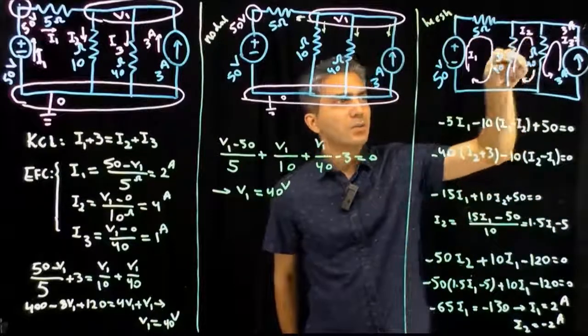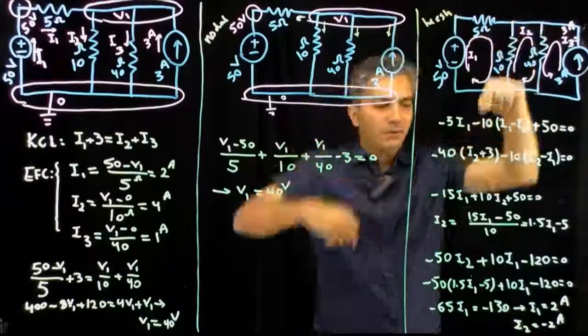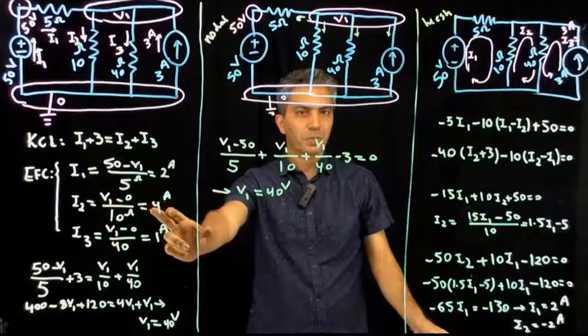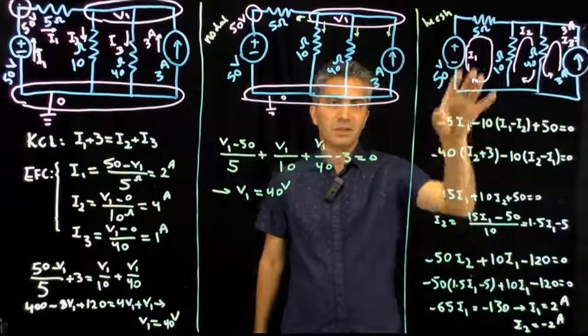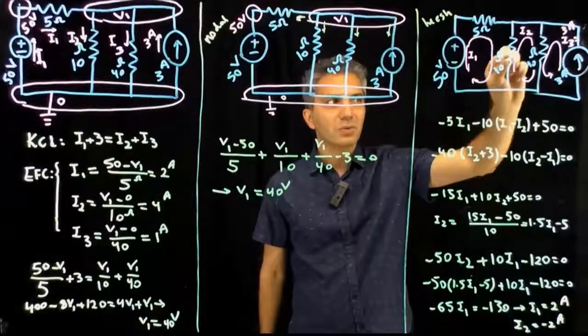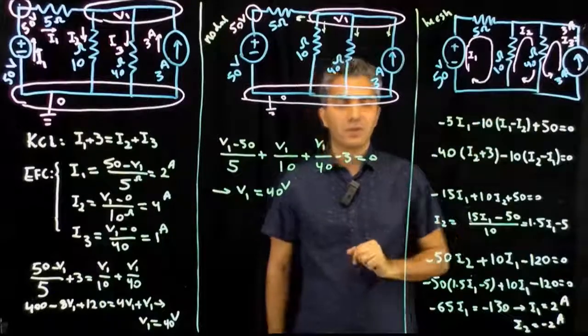In other words, I2 is also going the other way around, so the 2 add up and give you the 4 amp, which is the same current that we calculated before. Okay, so you still have to do some more analysis in order to specifically calculate the value for the currents of each component.